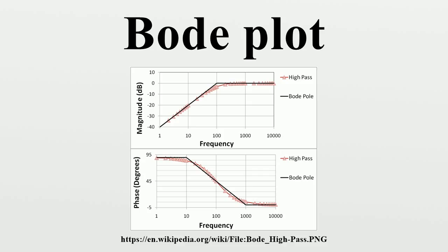This idea is used explicitly in the method for drawing phase diagrams. The method for drawing amplitude plots implicitly uses this idea, but since the log of the amplitude of each pole or zero always starts at zero and only has one asymptote change, the method can be simplified.